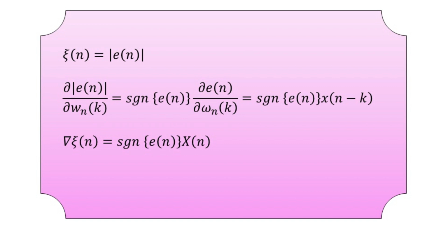So this was the example where we made use of the sign of the error signal. Now, in order to reduce the computational complexity, there is a simplified way of using the sign of the data signal also. This is possible for the data signal, error signal, or both.